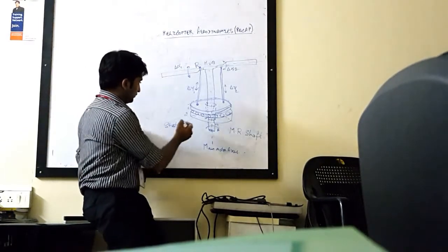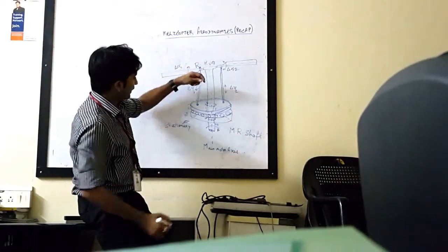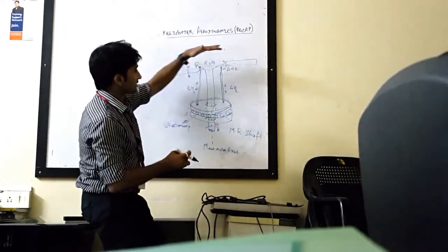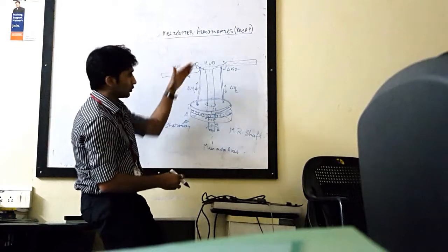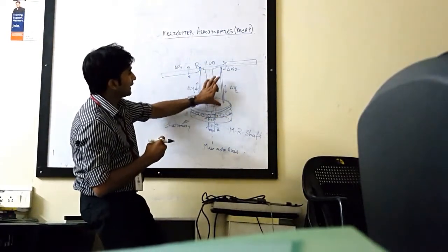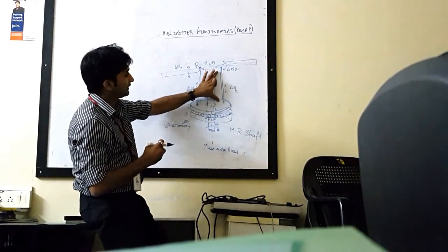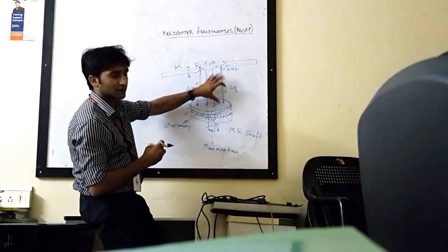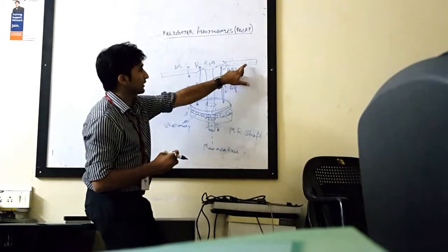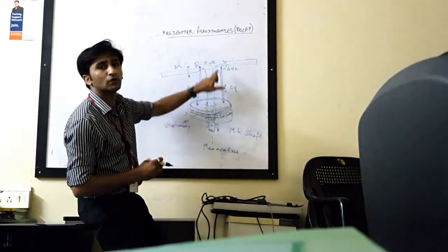Okay, now as the main rotor shaft rotates, the rotor disc, the rotors are set into motion. Now, once the rotors are set into motion, the top plate and the rotors are connected by the control rods. They are locked in terms of relative rotational motion. So now, as this rotates, the top plate should also rotate because they are connected through the control rods.